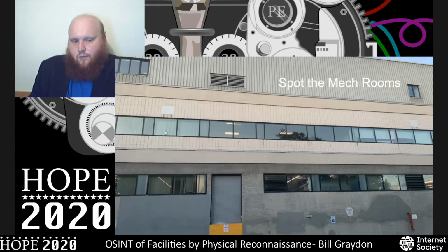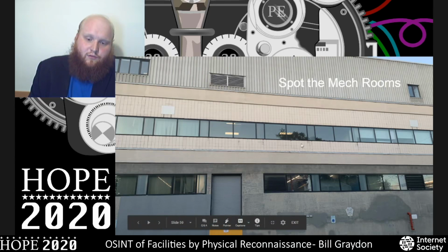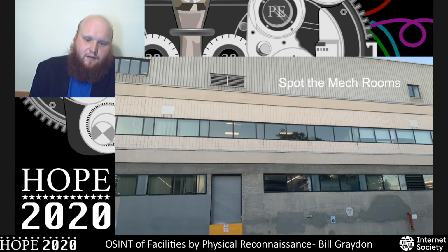On this second floor, we can see this continuous fenestration, and we can see everything within it. Also note that the walls are actually visible, so we can start building up the internal layout of that second floor. But we can see there's no mechanical room there. On the third floor, we have this louvre and a large area without windows. So that is likely a mechanical room as well. Given these two, there's almost certainly a riser shaft of some sort connecting these recessed into the building. We know it's not on the edge, of course, because of this fenestration.